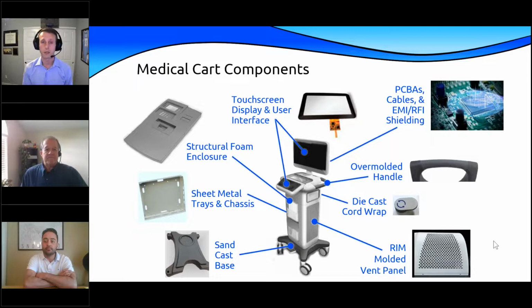But it also needs to be a nice cosmetic base because it's customer facing and it's a big part, and it's one of the first things you see when you walk up to the cart. So we used a nice cosmetic casting process here. It's a sand cast base. We did it in zinc to give it a little bit of extra weight, zinc instead of aluminum. It's a denser material. And then we were able to apply a nice cosmetic paint onto it after casting.